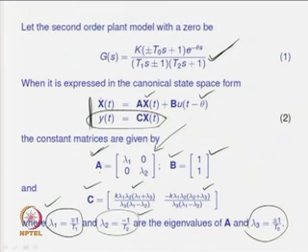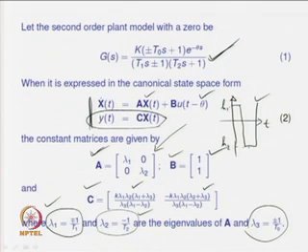What type of output signal does one expect when the asymmetrical relay with settings H 1 and H 2 is employed to induce sustained oscillatory output from the higher order system? The relay characteristic gives piecewise constant output, but the piecewise constant outputs are of different magnitudes.